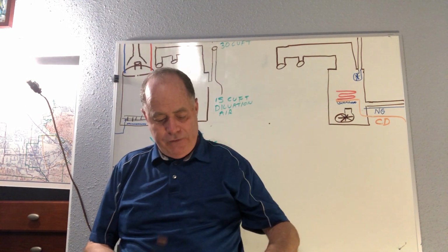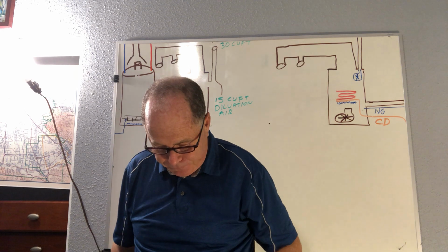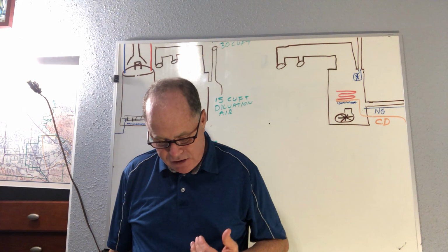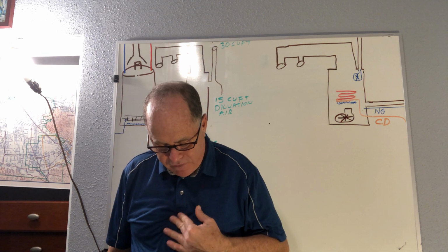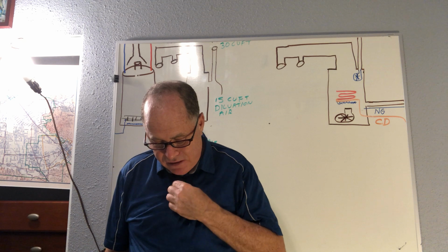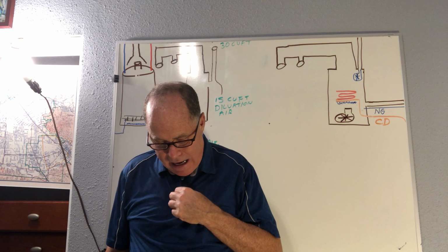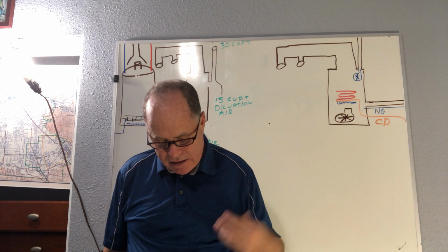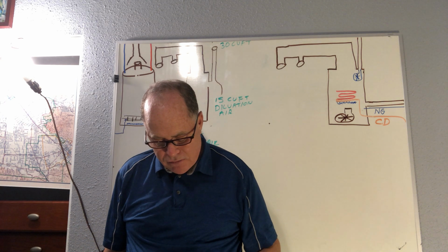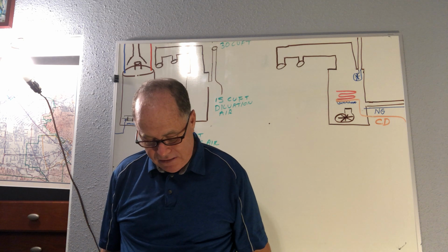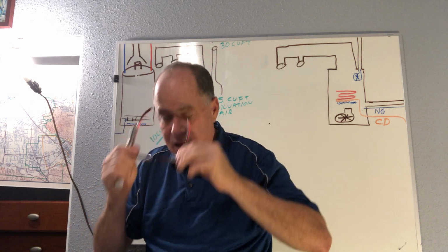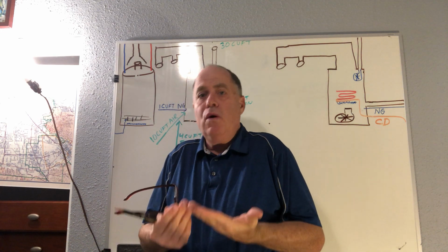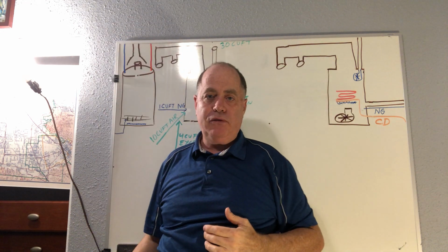Here, let me go over a few more points on the first page. It says here, the burning of fuel inside an appliance heats the air, causing it to rise within the appliance along with the products of combustion and exit through the flue outlet. As the hot flue gases exit the flue outlet and enter the vent through the draft hood, a Venturi effect is created, drawing cool, almost stagnant air from the compartment to mix with the faster moving hot flue gases. And you're getting this sort of thermosiphon action where the cooler air is being drawn in below and then rising up out the chimney pipe.